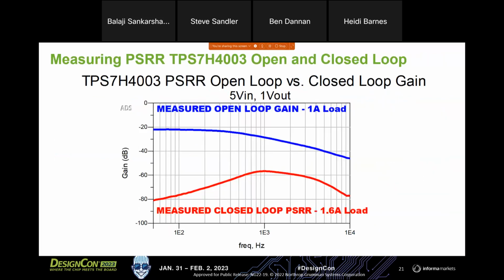And a step further, you can actually look now at the closed loop versus the open loop. This is why we want to measure the open loop gain: to characterize that VRAMP term accurately and ensure that when we tune that VRAMP and RI value accurately for a plant, we're using the right parameters for a plant. You can see here with the open loop gain, it doesn't include that closed loop PSRR feedback that's part of the VRM.